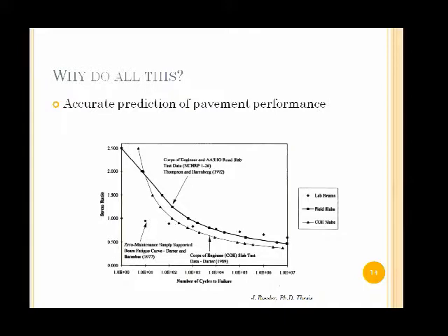And like I mentioned before, we need to be able to predict the pavement performance because right now we're slowly transitioning more to a mechanistic design, but the design was based on just flexural strength of a test beam. And that's sort of what this is showing. So a stress ratio of 1 is essentially saying that the beam to slab is the same. Like the load applied to the slab is the same as what the beam predicted. However, some slabs held 2.5 times more than what the beam would actually predict.